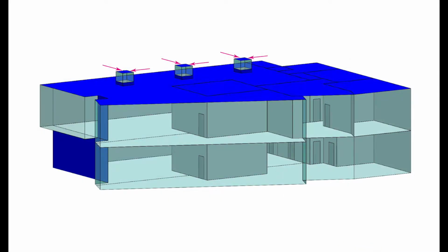Location 1 was chosen at the deepest place away from windows. That's for better air circulation and more even distribution of temperature and pressure. The first scenario at location 1 has 3 wind catchers with openings facing the dominant wind. The second scenario at location 1 has 3 wind catchers having opposite openings, where only one of the openings faces